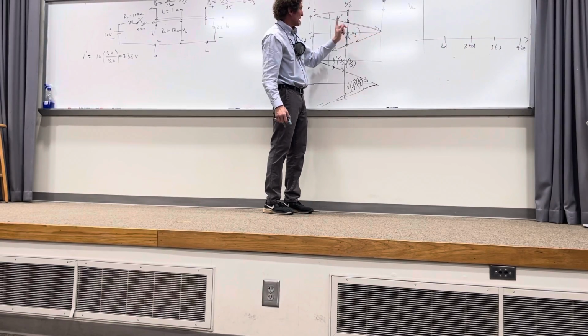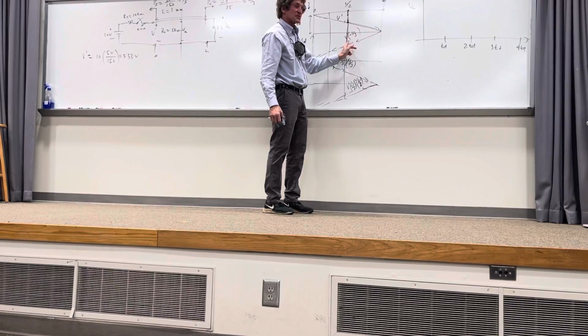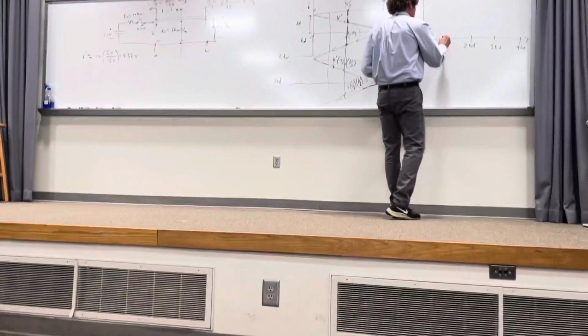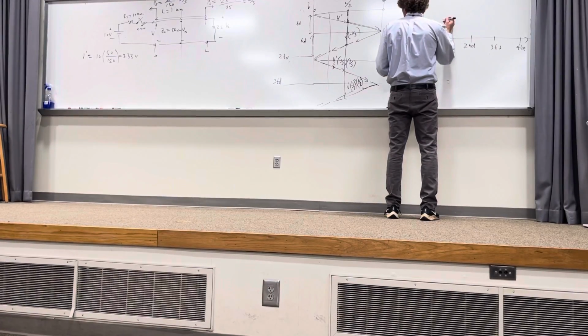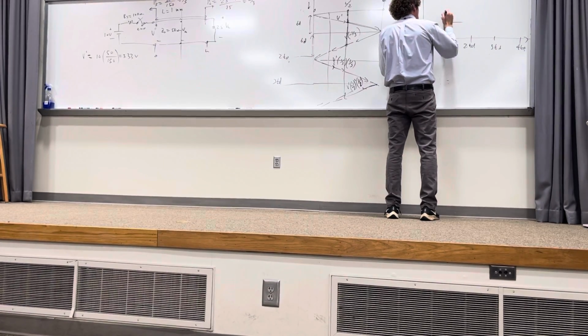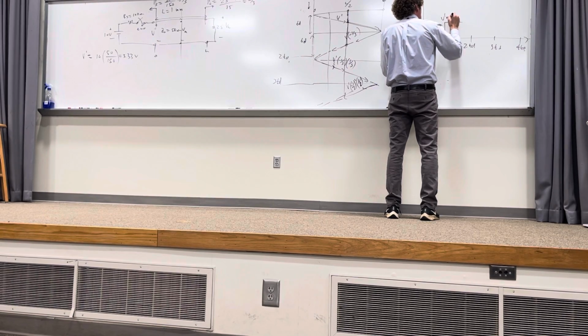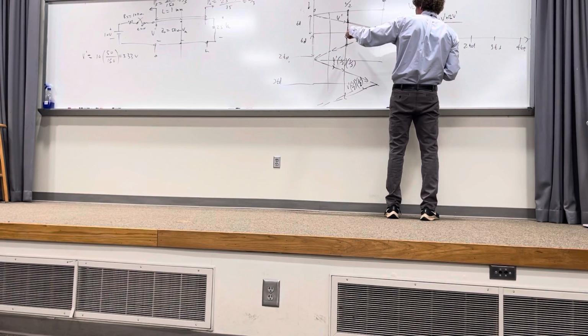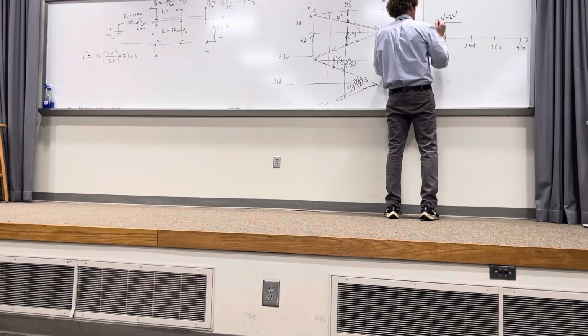It means you have to add V prime plus the reflection coefficient times V prime. Really, the first voltage that occurs at TD right here is going to go up, and this one will be V prime plus the reflection coefficient at the load times V prime. Now for our case, since this is V prime and this is -1/3, it's going to be 2/3 V prime.